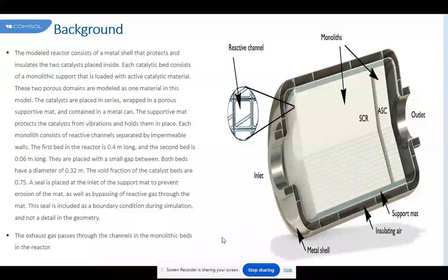Consistent with this simulation, a relatively small core with a higher viscous resistance deviates to the ring an amount of fluid that is higher than the proportional one, decreasing even more the space-time of the peripheral channels and damaging the overall conversion. At a core size of 50%, the conversion reached the same value obtained when using a flat 400 per 6.5 monolith. From that point, conversion increased practically linearly with the core size.